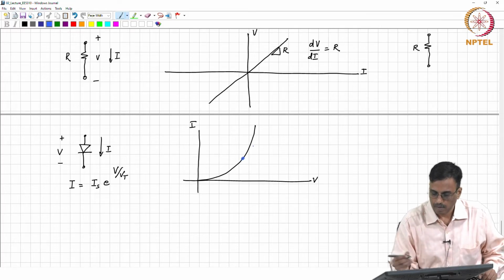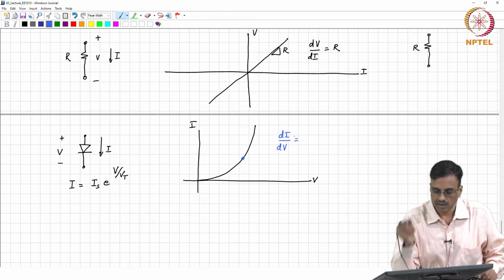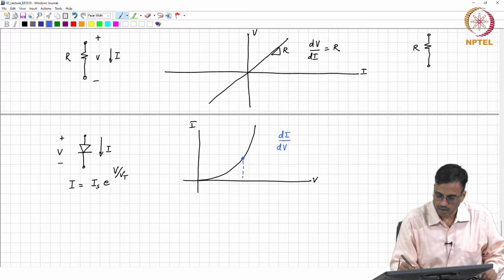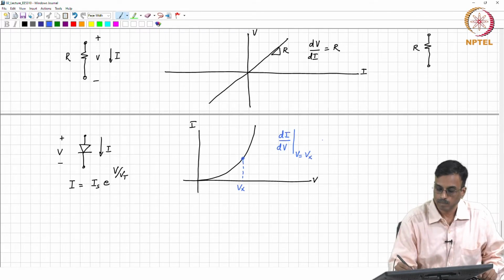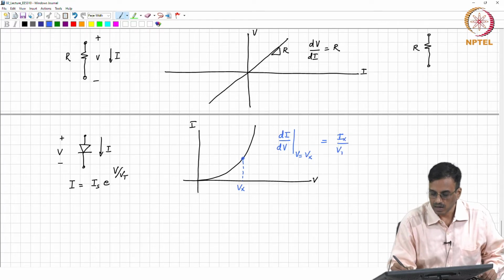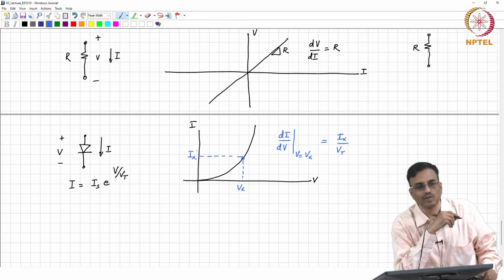what comment can we make? dI by dV at an operating point, say Vx, is nothing but Ix over Vt, and given Vx you can find Ix.